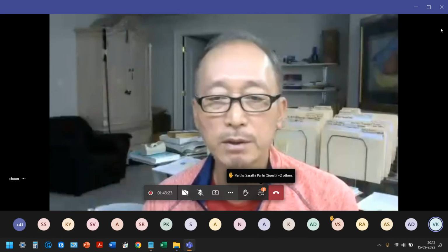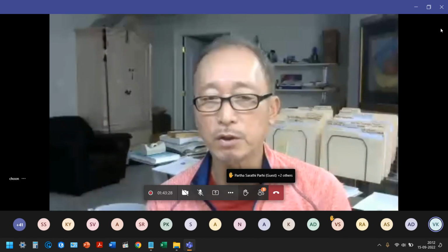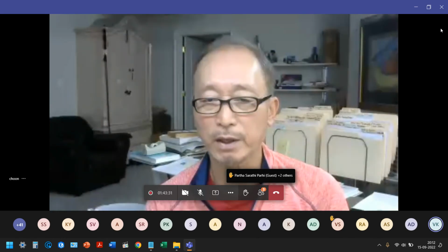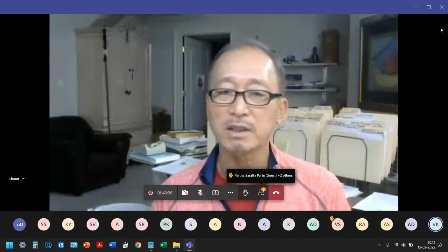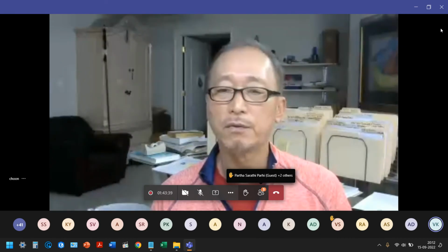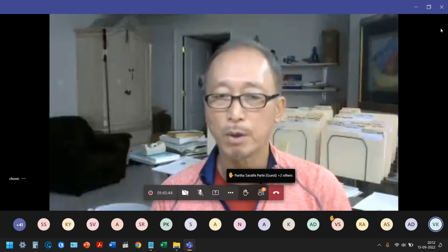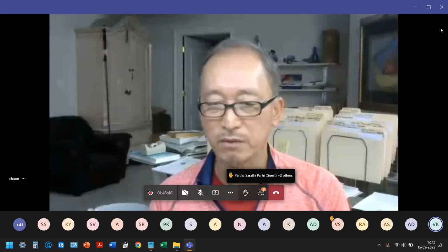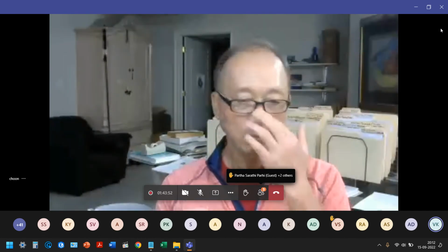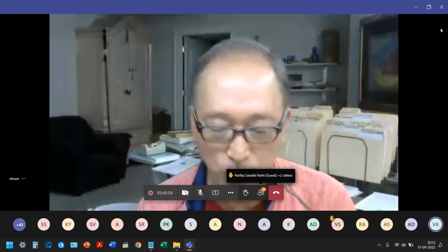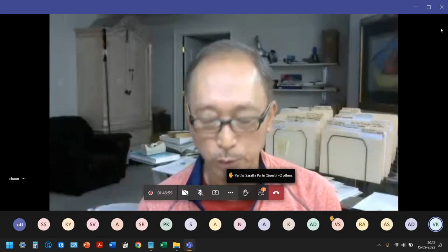Near field and far field effect and their removal. Well, you cannot remove or attenuate or minimize the near and far field effect. The best all you can do is select the optimum field geometry, in other words, the optimum distance of your shot point. But this is not that severe, so the rule of thumb is about 25% of your total receiver array length to be your shot point.